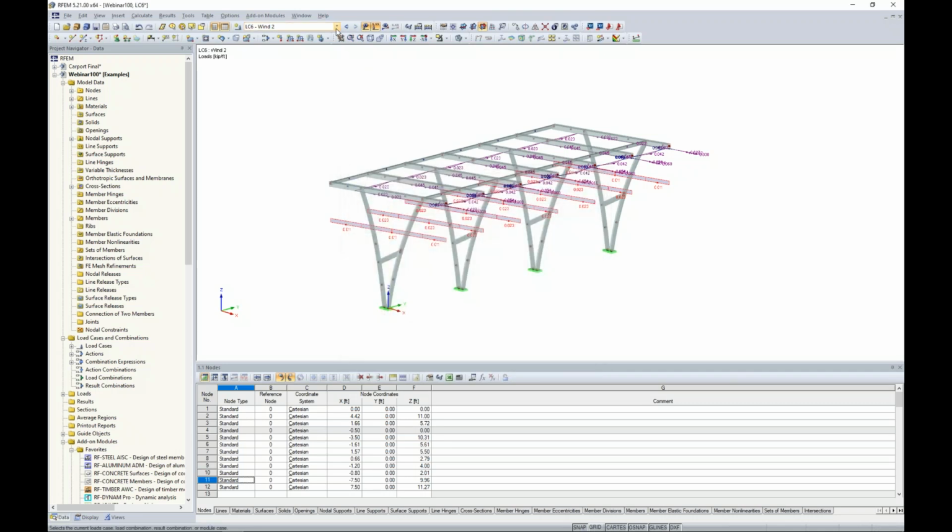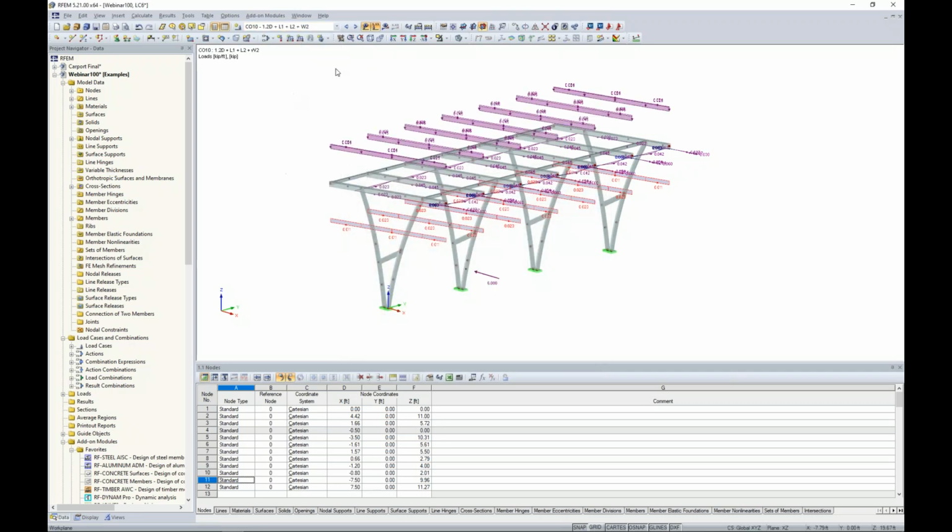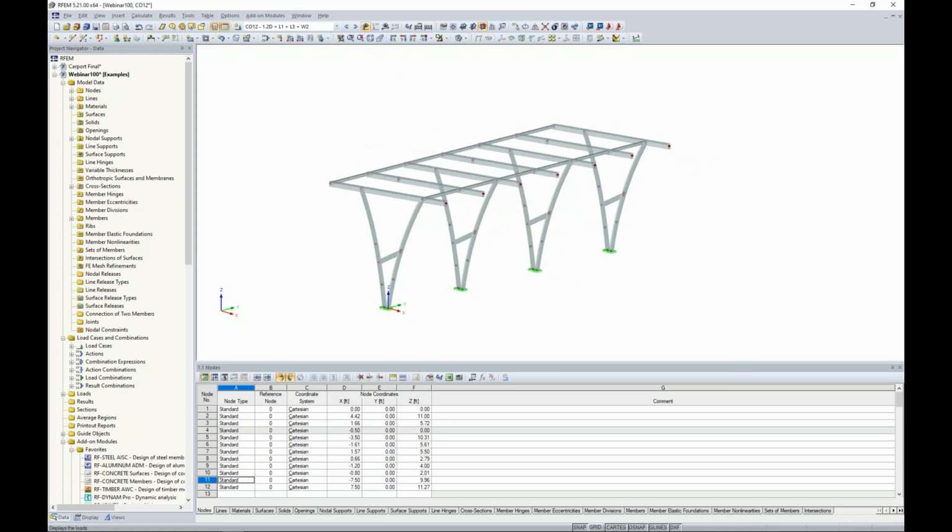So now that we have defined all of our different load cases, we actually can scroll through to the different load combinations and see these applied to the structure at once, including live loads, impact loads, wind loads. Everything is shown here. Now, before we are ready to run our analysis, there is one thing that I want to discuss from the ADM, and this is the stability requirements according to section C2.